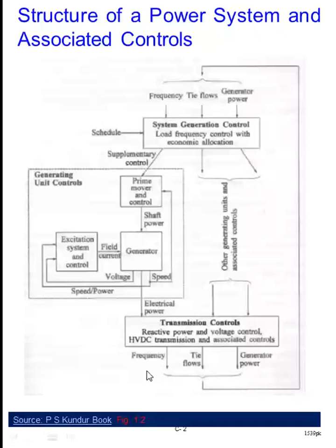And thus, if I say that there is a power flow from one area to another area, we are actually concerned about the amount of power flow in the tie line that connects the areas. And we also want to know the amount of power generated by the power plants or the machines and so on. So all this information we have to know. So, right: frequency, tie line power flow, and the power which is available at a given bus. All these are measured.